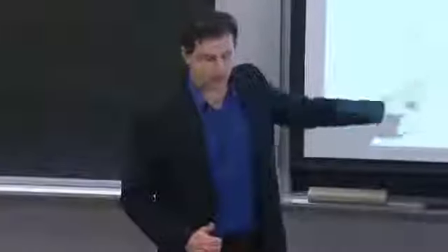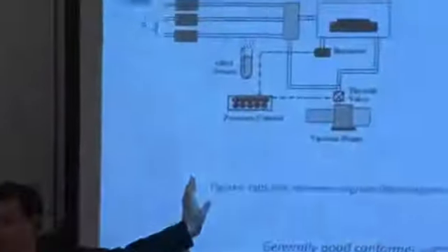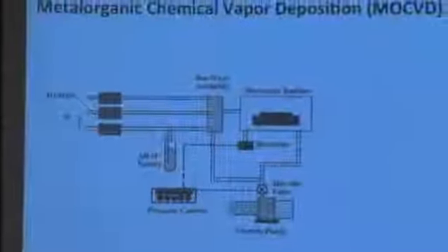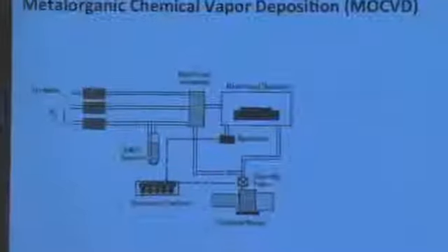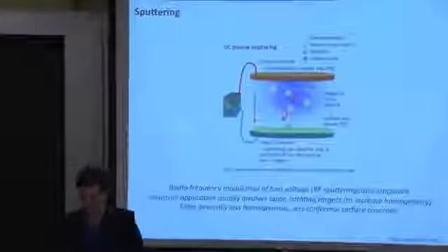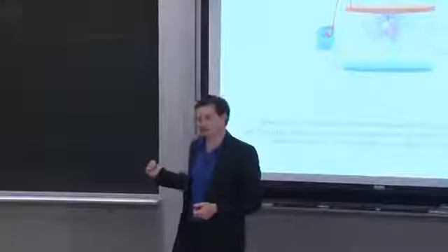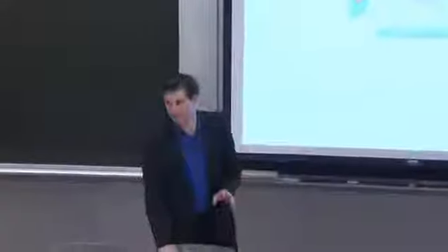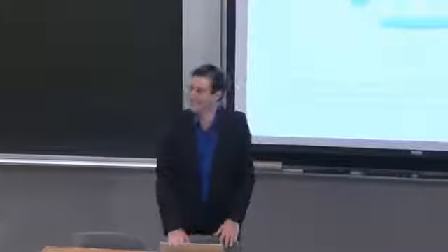So from an MOCVD point of view, you could do a distillation process and increase the purity of your precursor gas and avoid that. So I think two big reasons why MOCVD can produce higher purity films than a sputtered system: one is the quality of the target, and the other, I think bigger parameter, at least in our growth systems, is cross-contamination. And whenever you deposit, say at EML, they have a sputtering system there from AJA, or over at Harvard CNS, there's another AJA sputtering system there, you're going to get cross-contamination. Just look through the logbook and see what people have tried to deposit. It gets kind of scary.